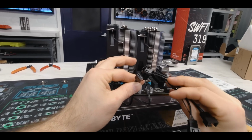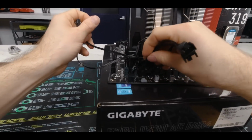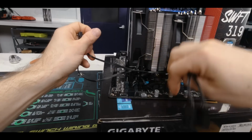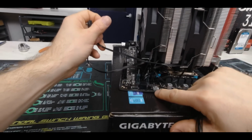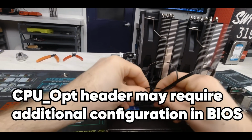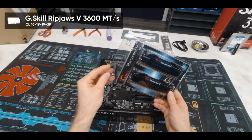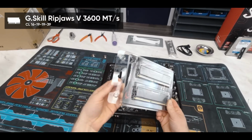Finally, connect the cooler's fan cable to the CPU fan header on the motherboard. The header is a port on the motherboard usually found close to the CPU, and if you're using an AIO, you might want to do the CPU cooler as one of the last parts after plugging the motherboard into the PC. Step 3. Installing the RAM.